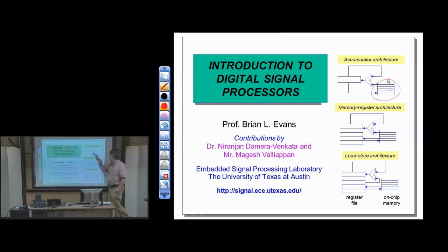You always had, though, to bring in the data through the accumulator. You had no choice, and this made sense because we're constantly doing multiply-add. So either we bring it through the accumulator and add 0 to it to keep it unchanged, or we put it in a multiply-accumulate. We might do a multiply earlier, and we might add something to it. It just depended on how we brought it in.